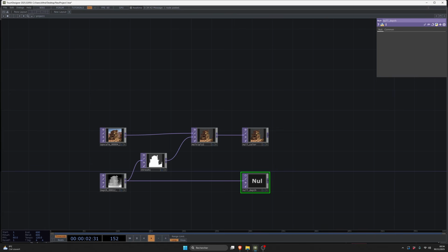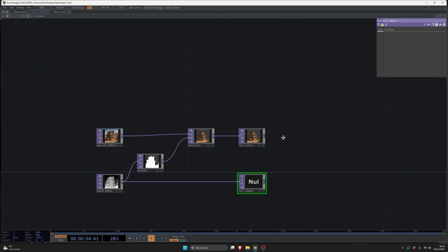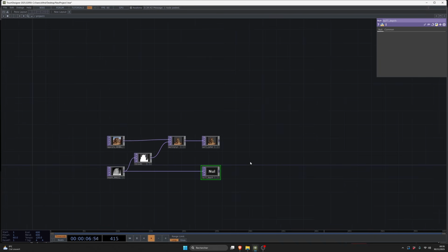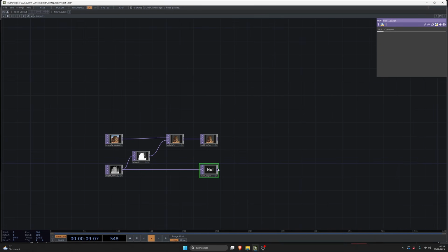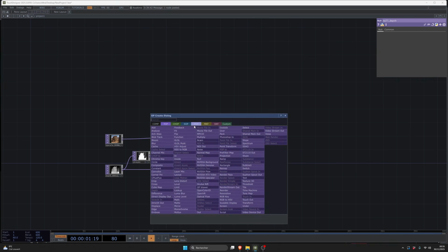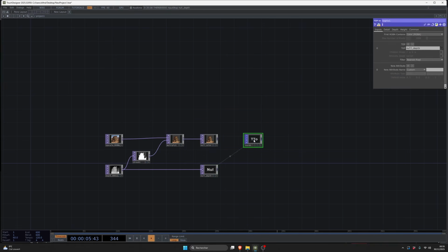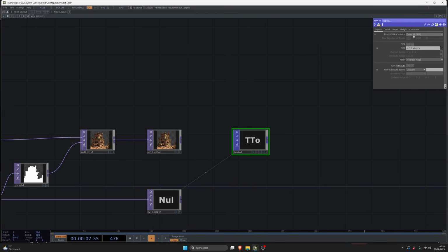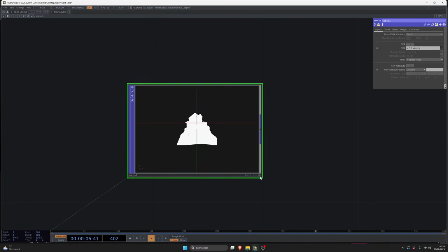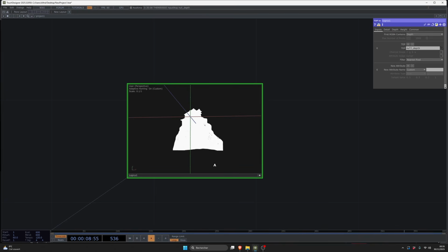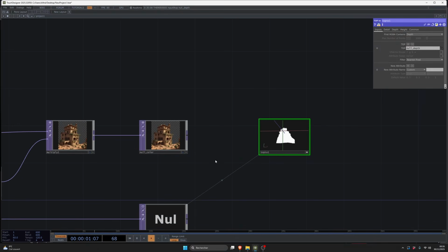And here we are going to see the power of the POPs. After the depth, we right-click, choose POP, and do TOP to POP. In the first RGBA, we choose depth, as the first RGBA contains depth and the TOP is depth. Now we only have the depth information, and what we want is to have the color information as well.